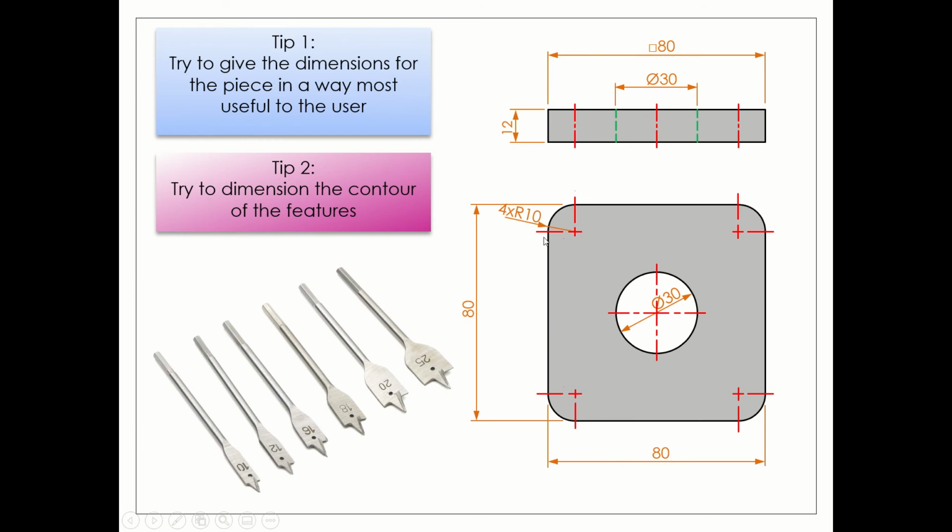And you could go one step further and say, well, look, we could dimension the radius 10 there for the actual fillets in the corner, but now you're really getting silly. That's hard to read now. So these dimensions up here do the same as the ones down here, but way, way more difficult to read. And again, that's where common sense has to prevail. Make the drawing as easy to read, dimension the drawing where you see the shape of the object.